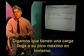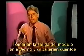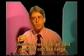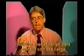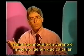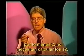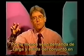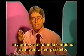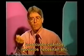So let's say that you've got a load that peaks in the winter time. You would look at the output of your module in the winter time and calculate the number of modules you'd need to meet that load. If you had different loads in summer and winter and different module output in summer and winter, you need to calculate at least 2. You don't have to do all 12. At least look at the load demand in the winter and the array output in the winter, and calculate the number of parallel modules. Then look at the load demand in the summer and the module output in the summer. Calculate the number of modules you need there.